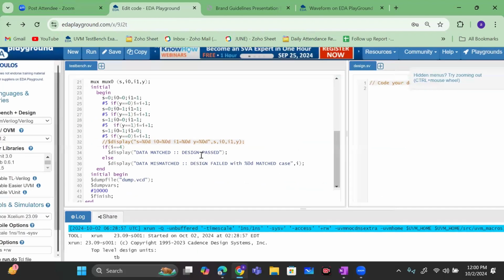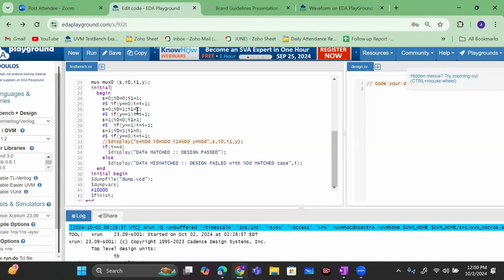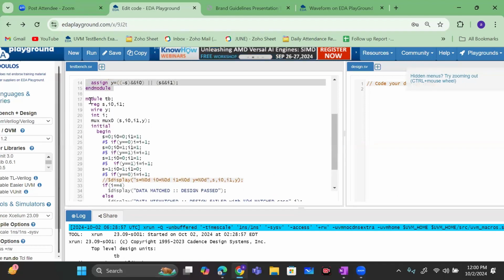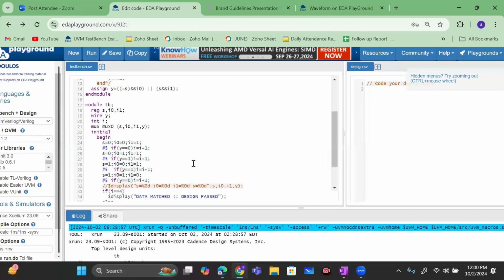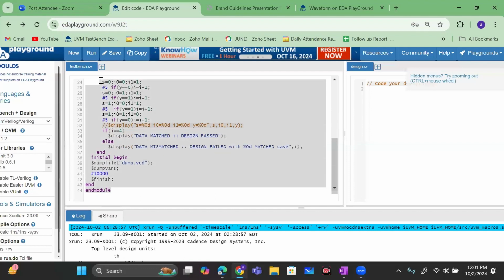So for that we have an extension which is HVL. HDL is specific to design only. HVL is specific to verification. V means verification. So the verification language, that means SystemVerilog, will give you a feature to write a test bench in a very standard order. That means there you have components, a reference model, monitor, drivers, and many other things. We have top, driver, interface, DUT. So that is the final solution for test bench.